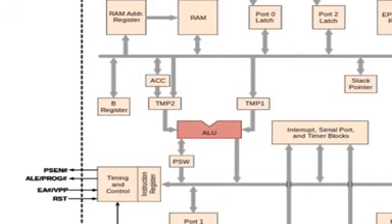Whereas in division you have two results, the remainder and the quotient. While dividing, even before execution, A holds the 8-bit dividend. After execution of the division instruction, the quotient is stored in the A register, whereas the remainder is stored in the B register. So the accumulator is an 8-bit register used for all arithmetic and logical operations.